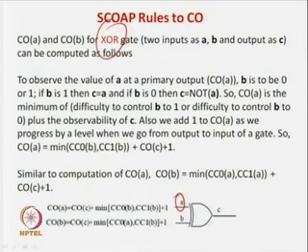Now, we all know that if B is equal to 1, then what is the value of C? C is equal to A bar, because we know that XOR gate is a controlled inverter. If you apply one bit as a 1, then you get an inversion. So, say if you apply a 1 over here and let A be 0. Then 0 and a 1 will give the value of 1, so A prime. Now, if A is 1, then 1 and a 1 you get a 0 at the output C, that is again equal to A prime.